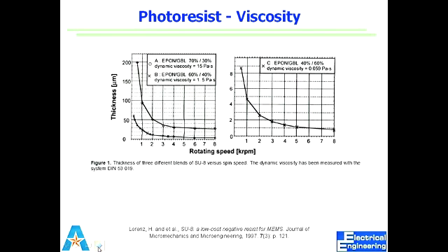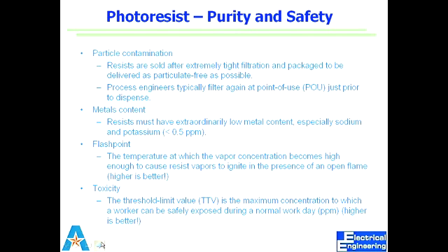So viscosity has a direct effect on what thickness we can make, and that thickness is, on the other side, a factor of what optical system I have and what dose I can give out from that, and that will define if I can reliably expose that thickness.